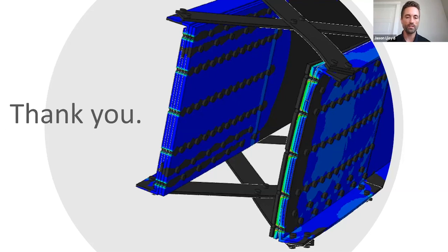When it comes to internal redundancy, so the IRMs, we've taken all of the FE work and we've done that in the background in developing the guide specification. And so for most internally redundant members, there are a couple of exceptions that we couldn't get to, a big one being tie girders. So if you have a tie girder for maybe a new tied arch design and you want to implement built-up construction in that tie girder, we didn't have the ability, timing, and funding to get to that specific type of member.